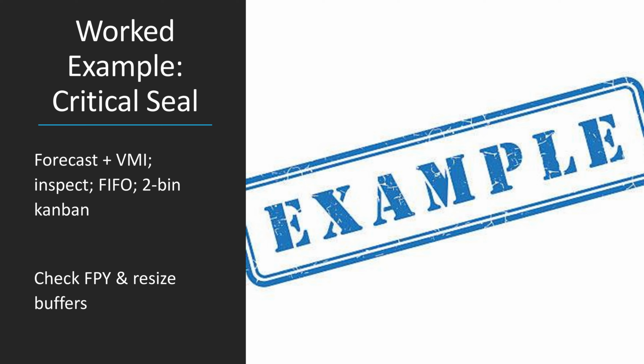Let's move on to stores. I assign a controlled temperature bin, label with part, lot, and expiry, and set FIFO lanes. I configure a 2-bin kanban size of 2 days of usage with a minimum of 1 day as safety. I add the seal to a kitting checklist for the pump line.